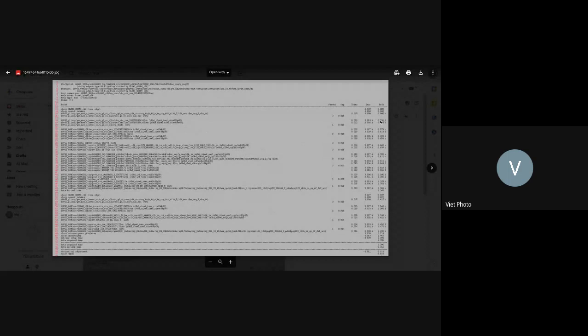This one is a 190. 190 is the arrival time here. And 205 here. 16 picosecond here is the delay cell, the delay of this inverter. So because of that, you add it and you have 205.